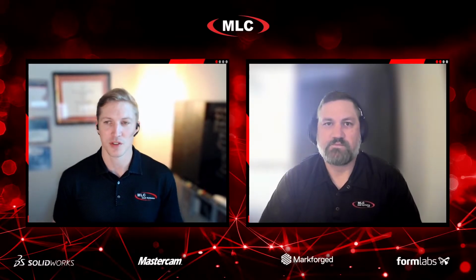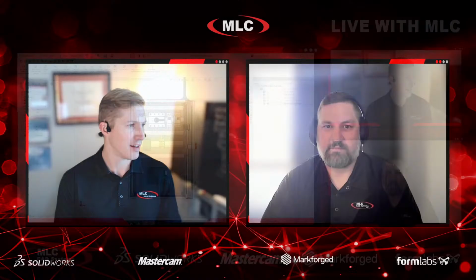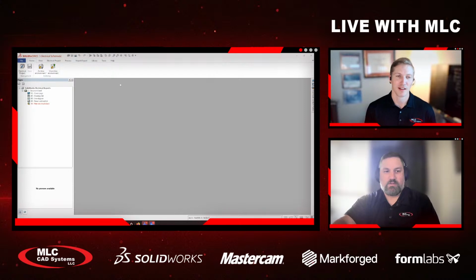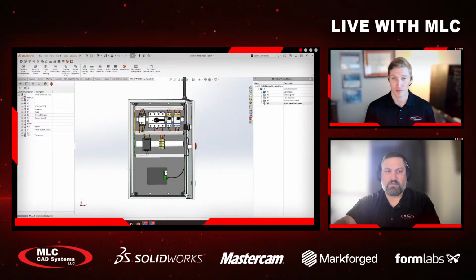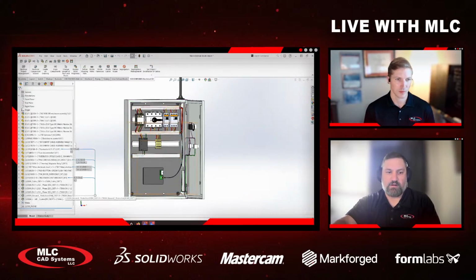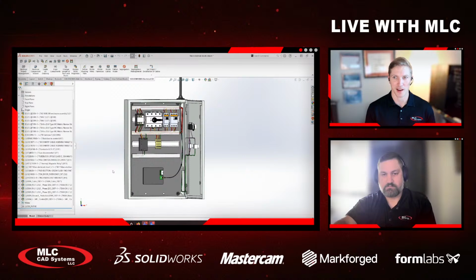Let's dig in then. I'll pull up your screen here, and it looks like you've got the schematic program open. Yes, this schematic program is tied to a 3D assembly. If I jump over into SolidWorks, you'll see that same component list on the left-hand side, and you'll see some wires have been routed using SolidWorks Premium routing. You can see those highlighted here. The wires have been routed in three-dimensional space so that we get wire lengths, and that's going to push into our wire report. So there's information coming back from the 3D side to the 2D.